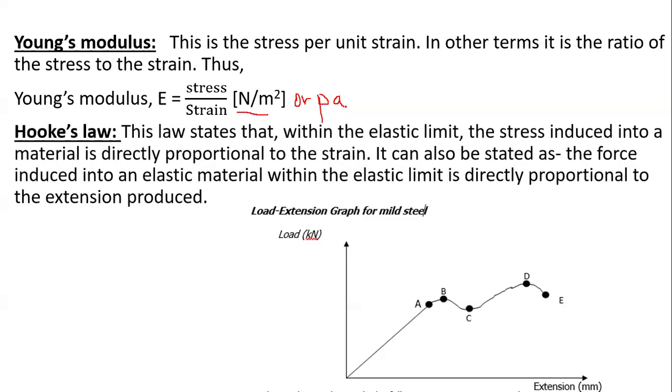Then Young's modulus basically is the application of Hooke's law. In Hooke's law, we say that stress is supposed to be proportional to the strain on one condition, that you're still within the elastic limit. You may decide to state Hooke's law in terms of the stresses, or you may do that with a force, where we say that the force is supposed to be proportional to the extension, as long as we are still within the elastic limit. When we exceed the elastic limit, this law does not apply.